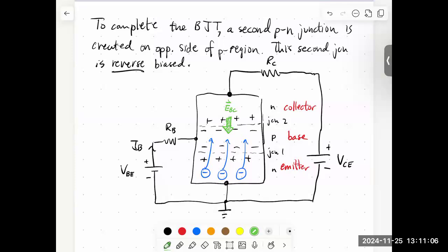Let's imagine here that we have these electrons that are injected into the emitter. So we have this clockwise current, remember, so that's electrons flowing counterclockwise. So we inject these electrons to the emitter. This is forward bias, so they go across this junction. The electrons that drift over here and see this electric field, what's going to happen to them?